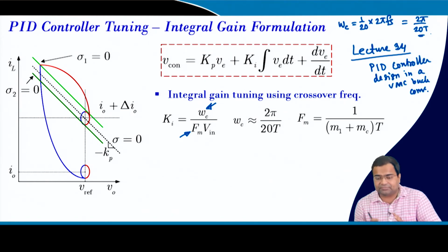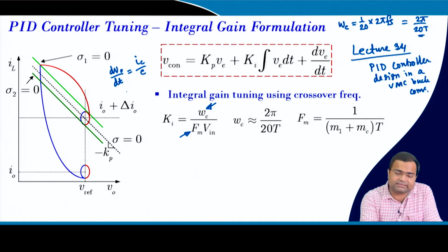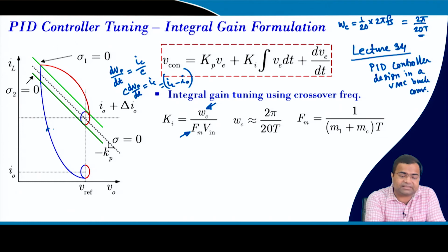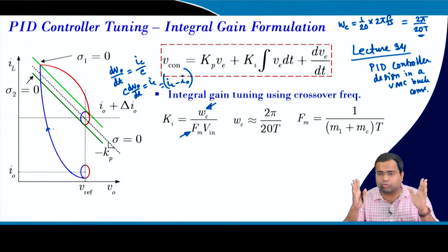Now, what is the modulator gain? Here we are considering the derivative of the output voltage, and in a buck converter the derivative of the output voltage, if you take dV0/dt, it is nothing but the capacitor current divided by C. If you take C dV0/dt, then it will be IC, which is nothing but IL minus I0, where IL has a slope, which is the rising slope M1, because we are talking about a step up transient, and this is particularly the trailing edge modulator, where we want to decide the turn on time based on our switching logic, which will come from the closed loop system, but the off time will be decided by the type of modulator that you are using. For trailing edge, it comes from the total time being constant.